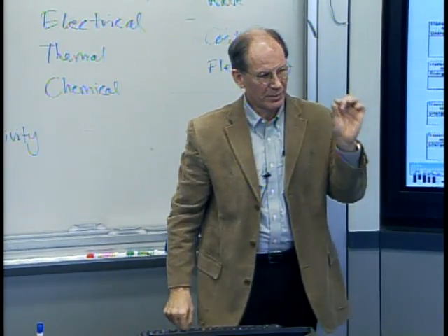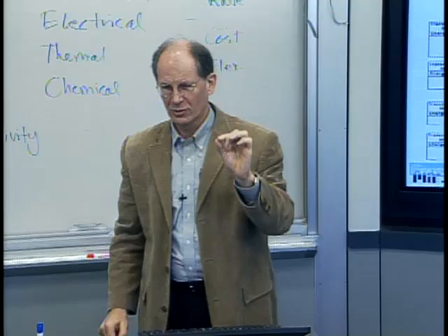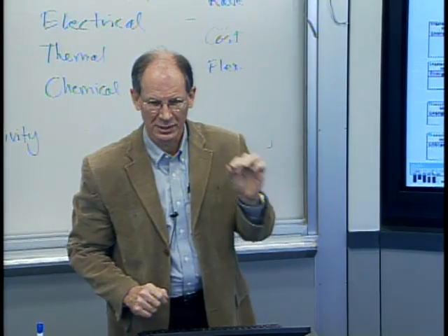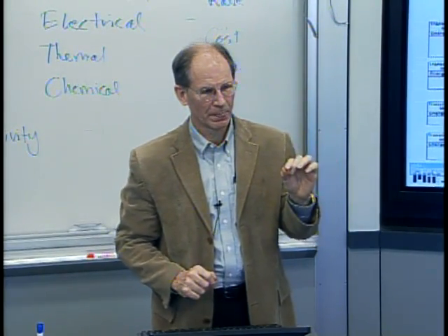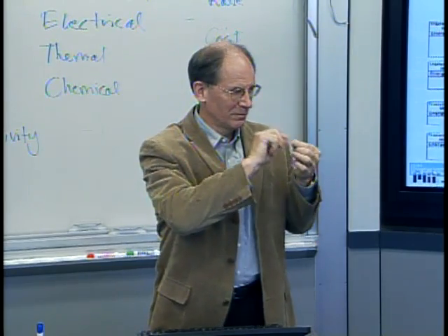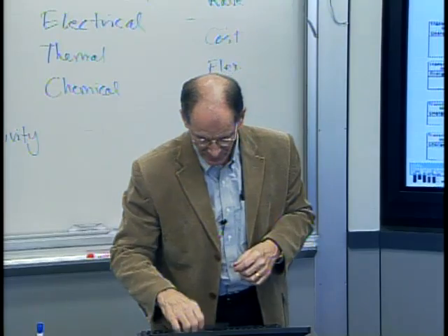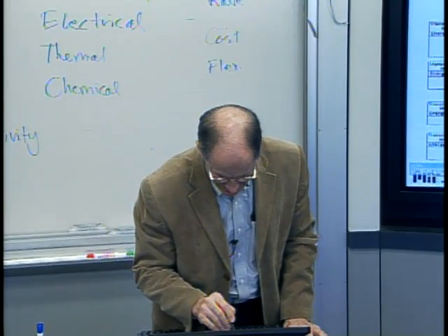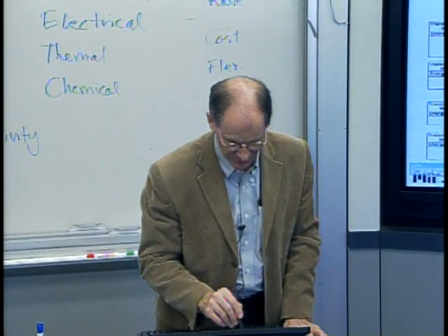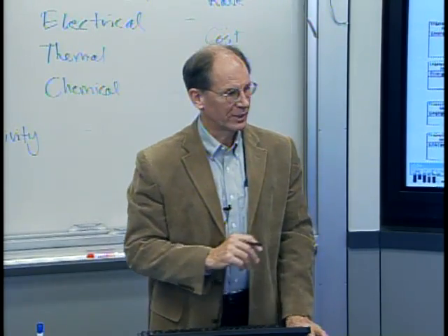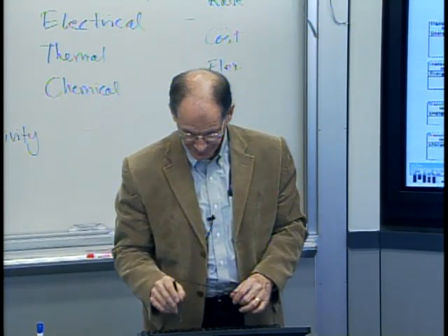So it's basically causing a chemical reaction, or in this case a polymerization reaction, at a very small area, by hitting it with the right amount of activation energy. Okay, so that's stereolithography. That would be a serial chemical formation process. You're going from liquid to solid.